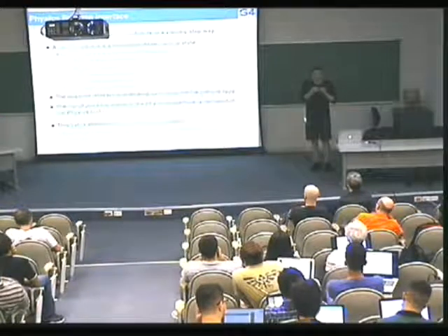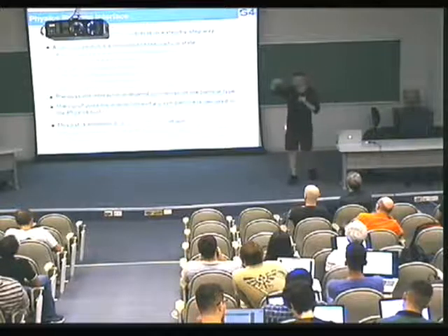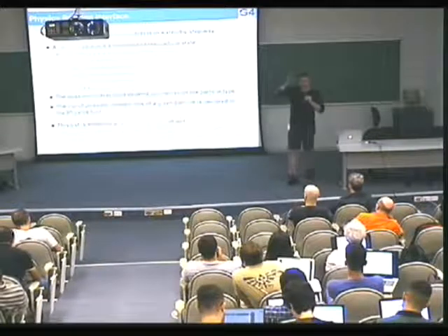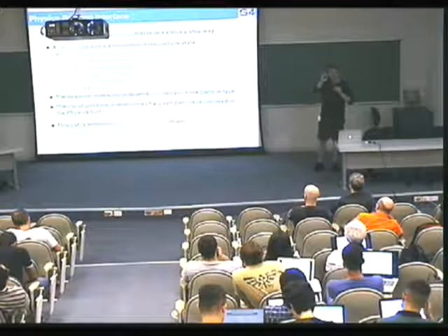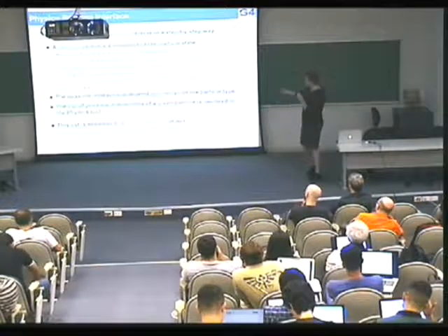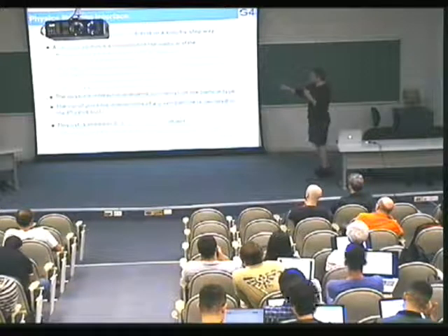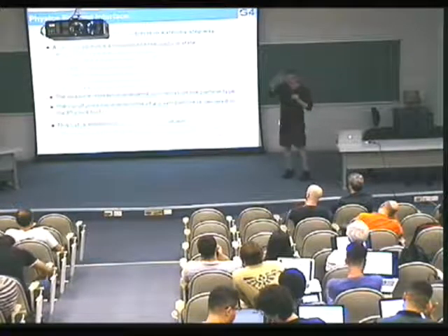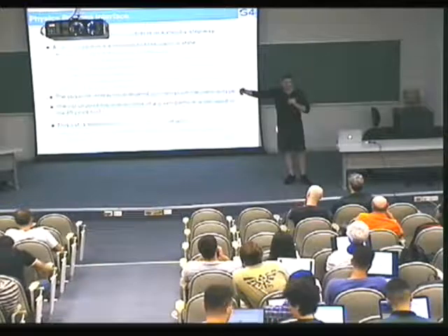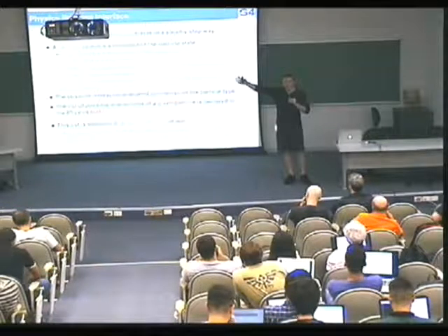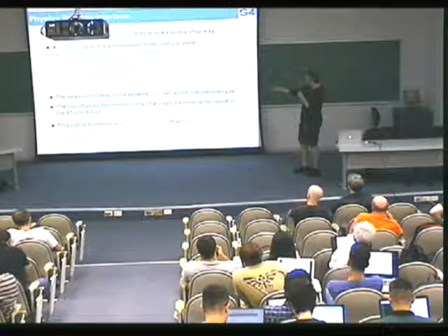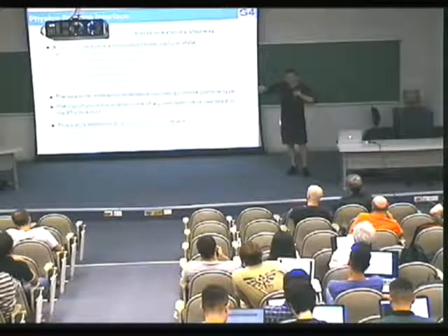So we have an electron, for example. And yesterday I showed that in your physics list, first you define a list of particles, like G4Electron, G4Gamma. And there is one electron. Okay, there is one gamma. Because each of the electrons are exactly the same. These properties are exactly the same. Now, there are other properties during the tracking: one given electron during the tracking can be at an XYZ position, or can have many different energies. But these properties are described in the G4DynamicParticle part of the track.